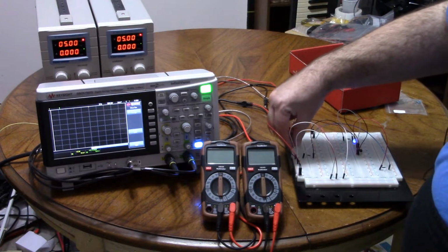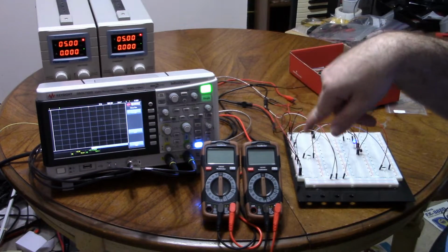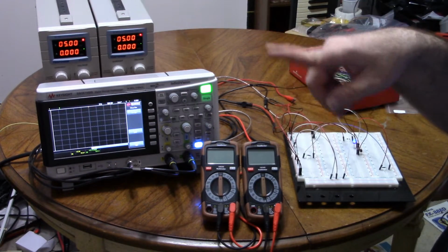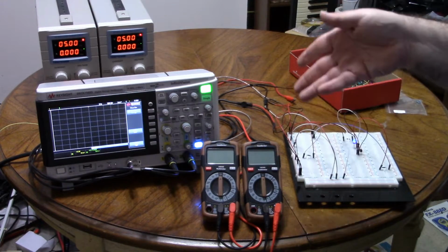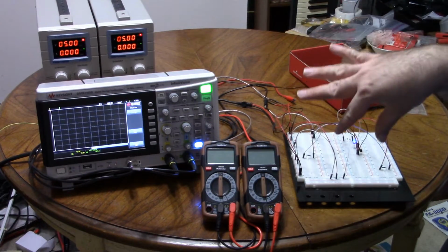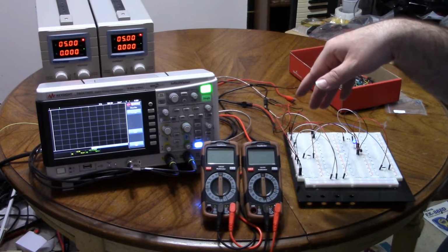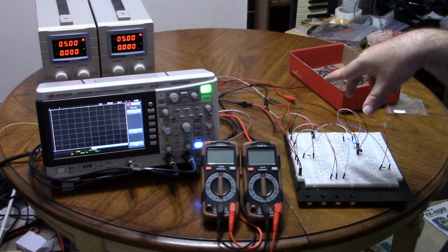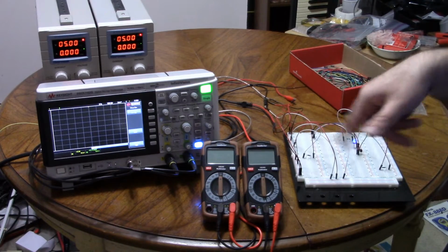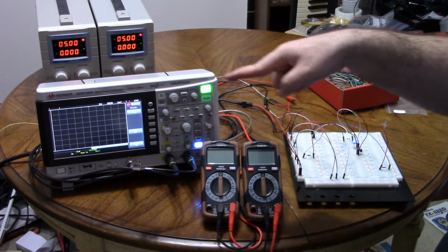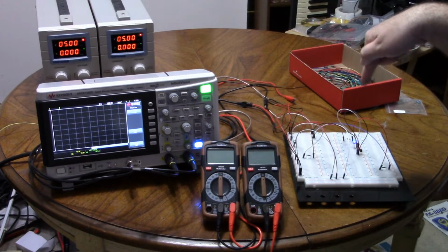What if I disconnect the signal? The LED turns off, because it still has to have the current through the base to emitter. It still has to have that circuit going on. It's not like a JFET that's default on and then you bias it to turn it off. Without a base connection, it doesn't matter how much you bias, it doesn't matter how much voltage you put in it, it's not going to transmit. It might explode, but it won't transmit. So I do have to have this 0 signal connected to turn the LED on.